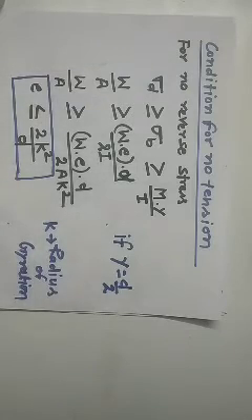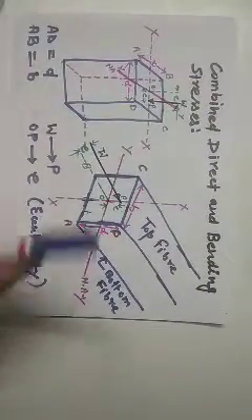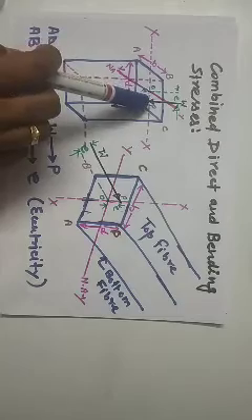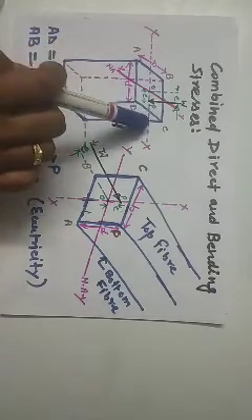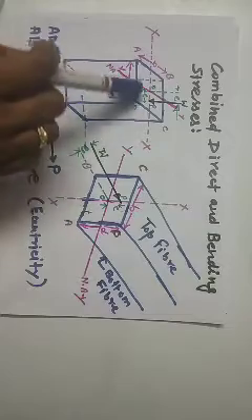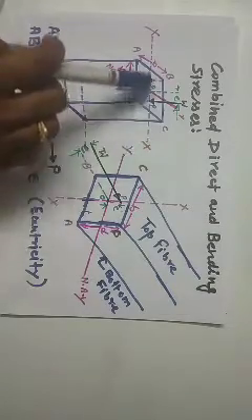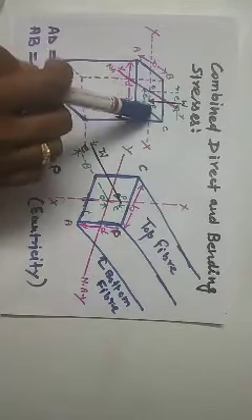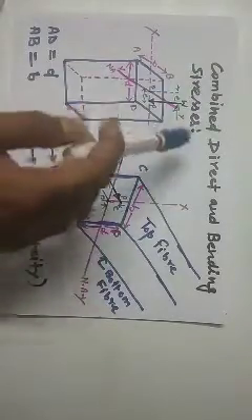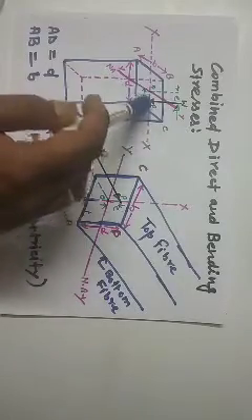we have taken D by 2, because if the column is of circular section, then Y will be D by 2, or if the column is of rectangular cross section, and the load is applied across this x-axis, at point P, which is on the x-axis, and this x-axis is parallel to the depth, because this is a rectangular cross section, then the value of Y will be D by 2.